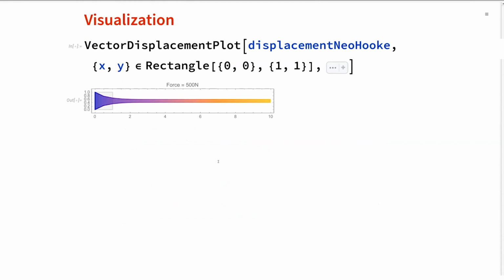So this is an example of a solver restart. The other option you have for these types of problems is to convert them into a pseudo time-dependent problem, and have the time go from 0 to 1, and slowly increase the force by multiplying it with a time t. So t at the beginning is 0, and then while the time increases, the force ramps up to 500 newtons.